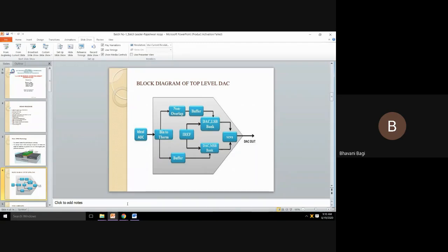The first 4 LSBs, B0, B1, B2 and B3, are sent to the binary weighted sub DAC. MSBs B4 to B11 are converted using the thermometer decoder sub DAC. The output of the decoder is sent to the buffer, which drives the current switches. The output currents are converted into voltage through the load resistor. The dummy buffer is placed between the input binary and binary weighted current cells. Some delays happen here between LSB cells and thermometer decoder cells.